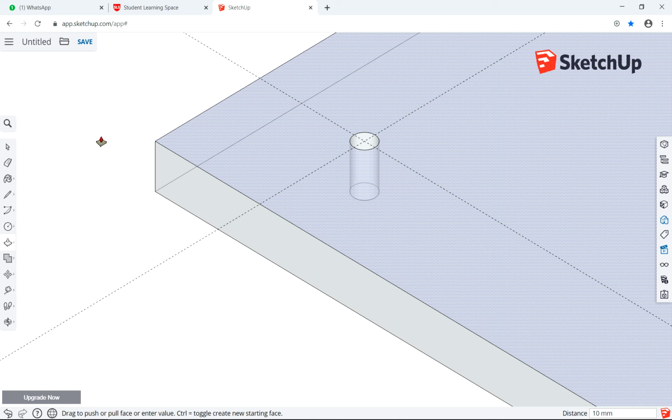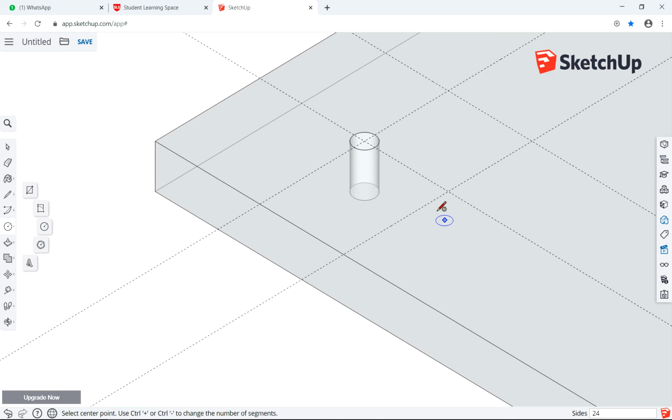So once I got it, let me make another circle, but this time I need to know the dimension. So again, how far apart is it from each other? It's about 20 mm. And then from here another 20 mm. So every now and then I need to make the same. So this one, I make another circle, diameter 2.5, then push and pull, go down by 10, enter.